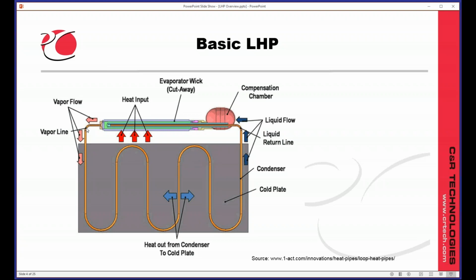But let's start here at this nice simple tubing with saturated vapor coming out through the system, gradually condensing, maybe at some point around here completely condensing, and then being all liquid maybe in the last part of this condenser, and subcooling a little bit and returning back into this assembly that we'll be talking a lot more about, the compensation chamber evaporator assembly, where all the vaporization and interesting things happen. The compensation chamber, by the way, I will be abbreviating a lot as the CC, because it's just difficult to carry around a term like compensation chamber over and over again.